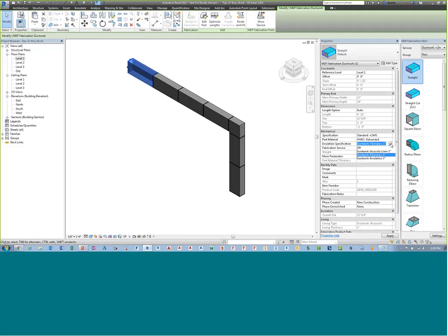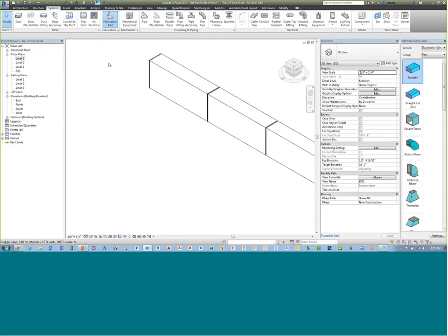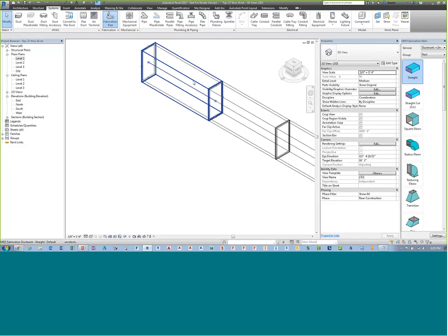The reason it does is because I actually modified and altered the database file prior to working with it here in Revit. And so I forced it to have an installation of something I created called ductwork fiberglass 1-inch. You can just switch it to whatever you want, and it will actually put it in. Let's go to a wireframe view. You can start to see that.